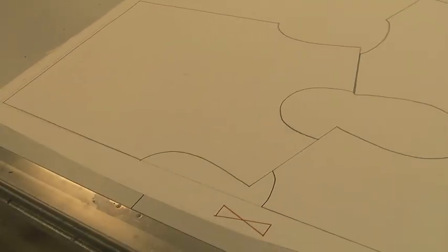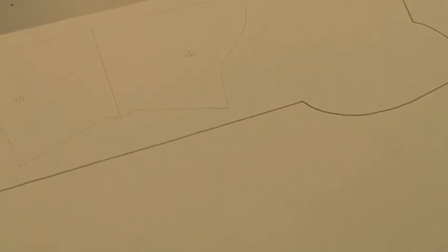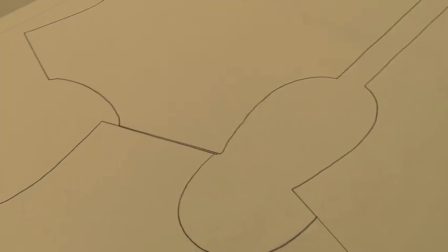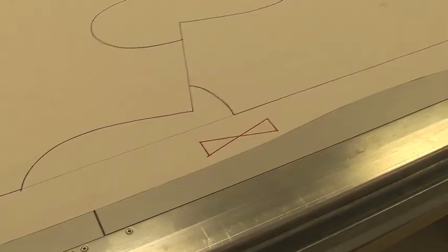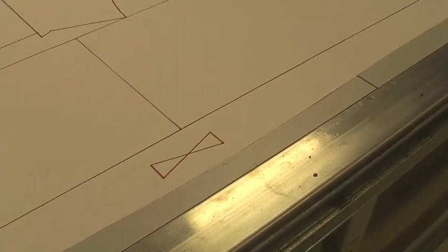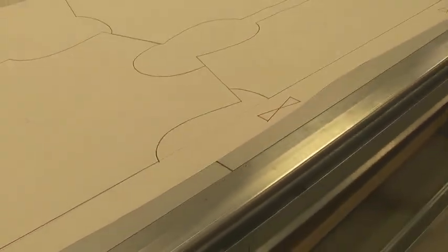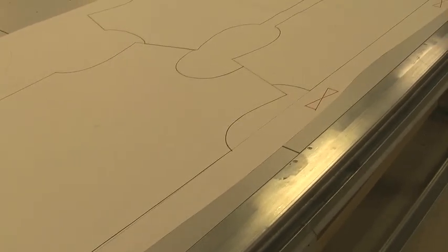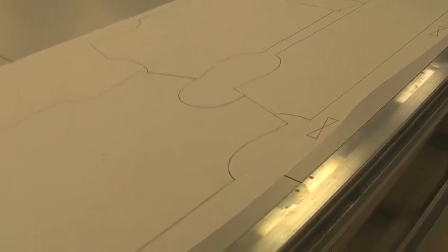Before I get started with that, I printed out a marker, and then I made it a little bit darker on some of these lines here so that we can see. Here's our splice marks in red, and then our pieces in black. So this particular marker has 3 splices, and we're going to use these indications here to show you how we use the Splice Mark feature when spreading with the XLS 125 using CutTicket.